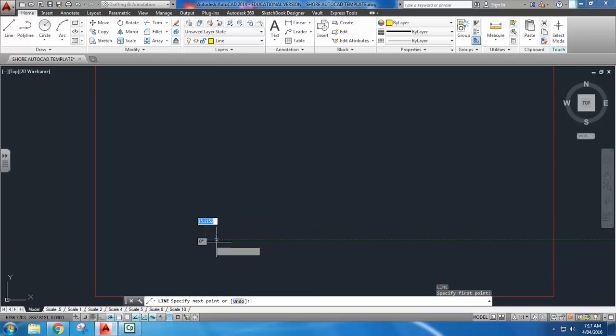So first we click, and then we drag in the direction we want to draw a line. So if we want to draw a line up, see the dotted line, the green dotted line, that snaps for us, and you can see it says 90 degrees on the screen. So now we know that's perfectly 90 degrees. Now if we type in the total length of the leg, using our keypad, 582, and then simply press enter.